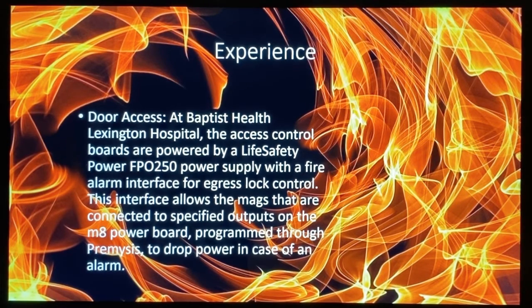Meaning whenever there is a fire alarm, the magnetic locks that we have, which we call mags, on either the exterior doors or just doors in general that break up hallways and sections of the building, basically any mag that we have throughout the hospital is connected to the fire alarm interface, which then allows that when a fire alarm goes off, it releases the power on those mags for free egress,